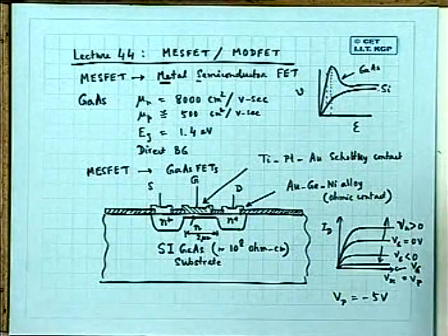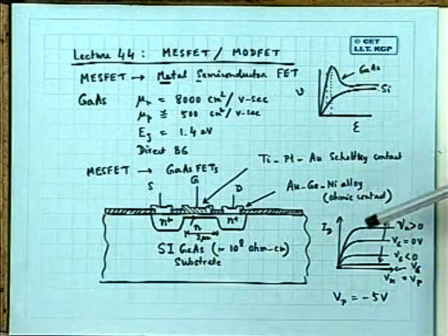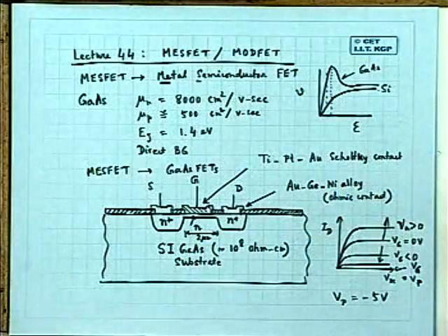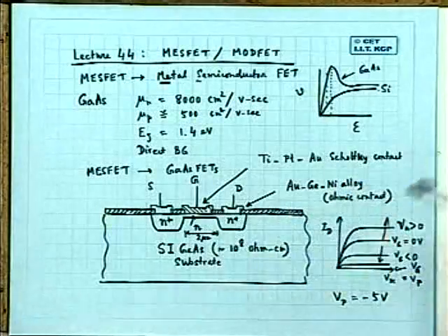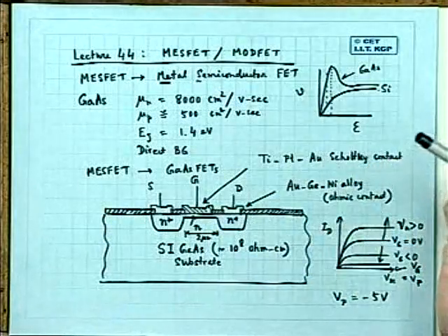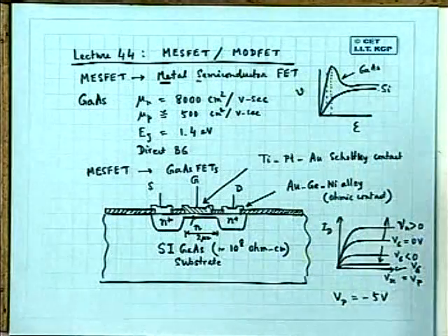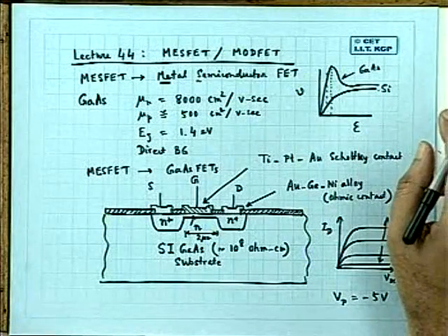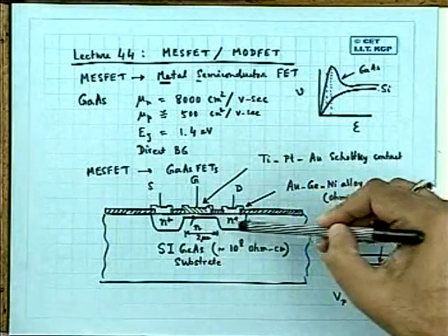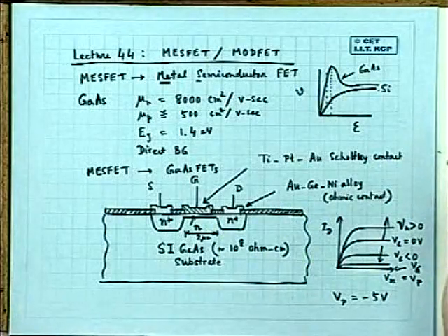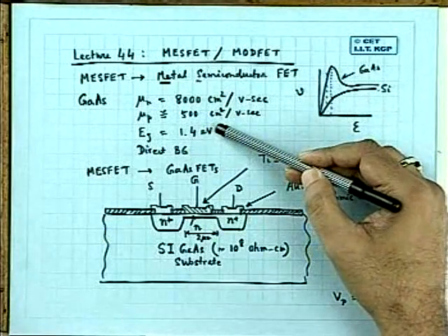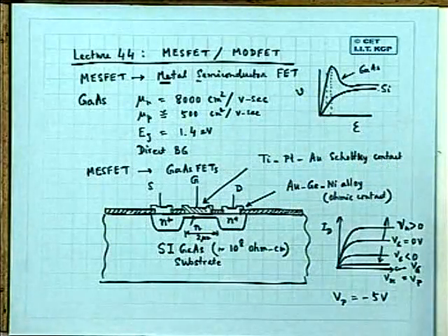In fact, that is what was revealed afterward. It was found that it is not only the transient delay along the channel, but also the charging time of the capacitors that become very important. The capacitance of these junctions, which account for the charging times of the pulses, has to be reduced. But with scaling, that can be done, because when the structure is big, these capacitances are also big. Though the intrinsic delay here is very short because of the high mobility, that is offset to a great extent by the bigger capacitances.